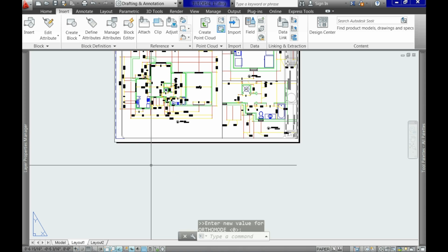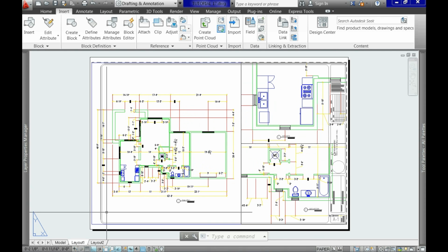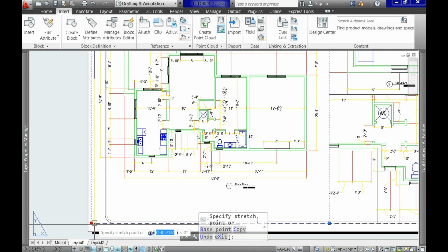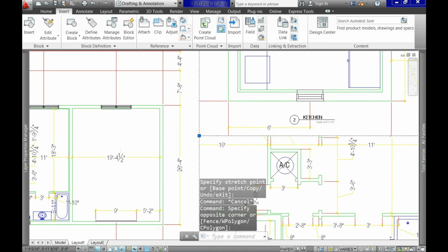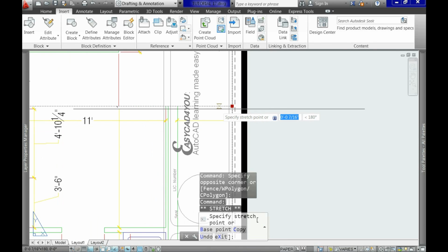Obviously, we need to adjust our viewports to accommodate all three of them. This will require some adjustments, so we need to play with all these viewports. In order for us to do it, we select them one by one, and then, using the editing grips, we move them to the place we want.